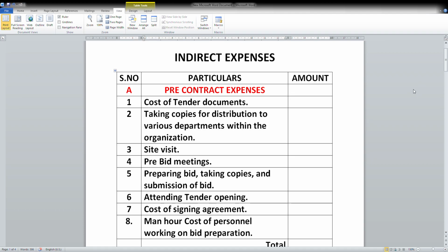Wherever the expenses are applicable, you can work them out separately and keep the account of indirect expenses separately. These indirect expenses can be on pro rata basis. It can be loaded into the unit rates. Suppose the indirect expenses are about 5% of the total cost, this can be on pro rata basis, loaded into each item of work under the head indirect expenses.